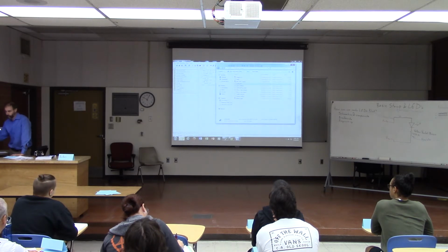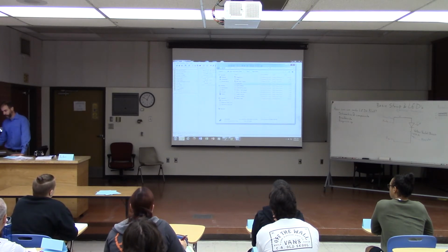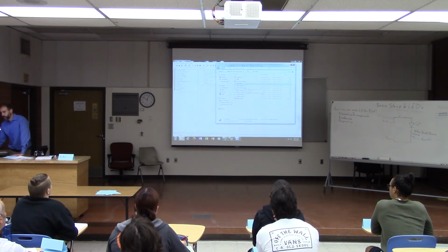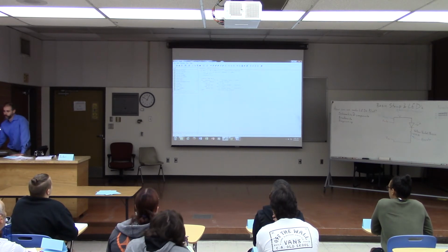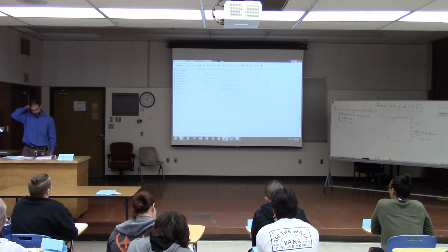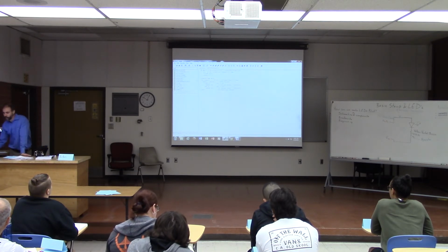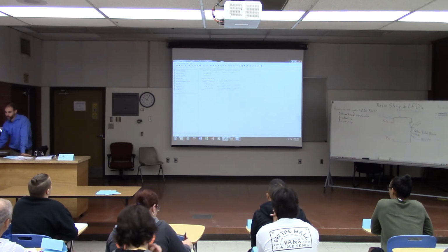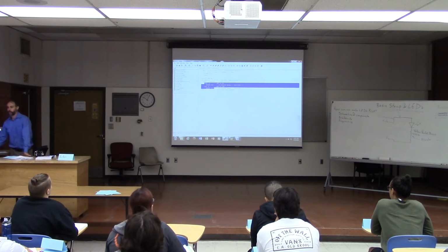We might want to have a program that blinks only a set number of times. So we can open up this other example program that is called LED on-off 10 times. And you can see here, we've still got the high 14, pause, low 14, pause. So this is just the same as we had in the previous program.